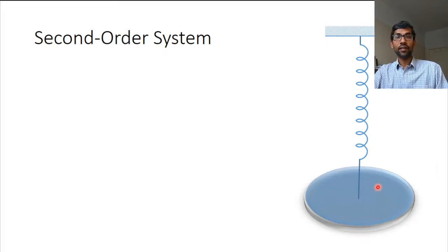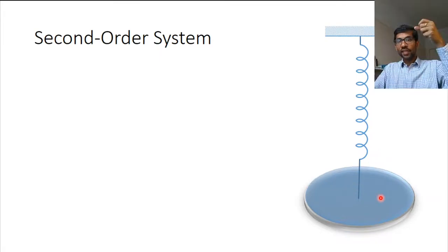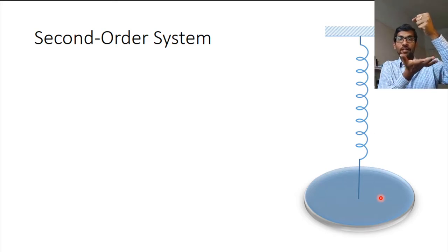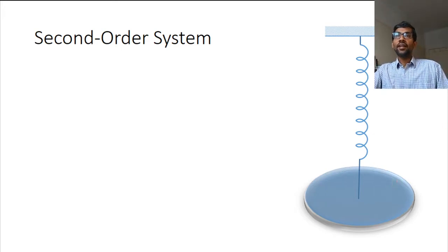Depending on the weight that we put on this plate, the spring is going to extend or contract. If you put a weight here, this is going to contract. If you take away the weight, the spring is going to pull the plate back up. If we measure the displacement from this point to the plate, we will be able to measure the weight of the substance that you're putting on this plate. So that's what the sensor looks like.